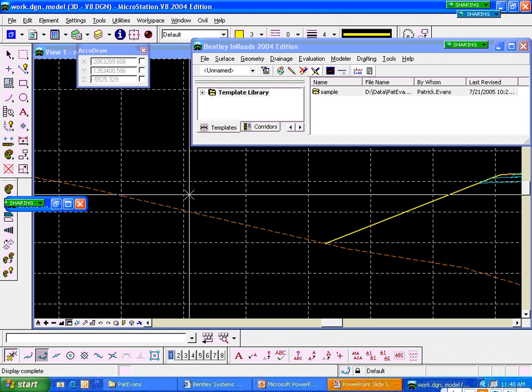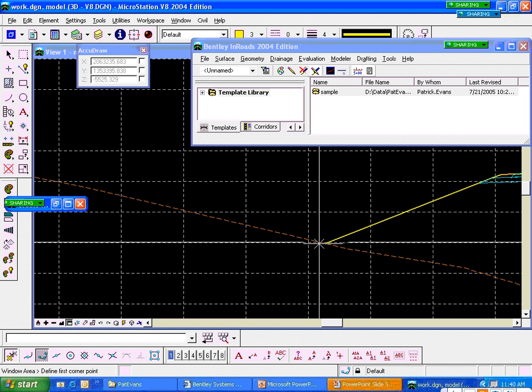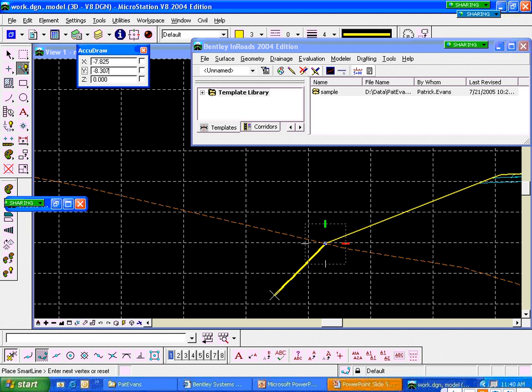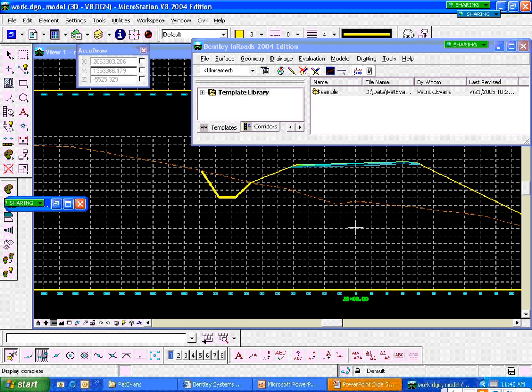And so really what I want to do is come over here. Let's window in a little bit. Since we are in a CAD package, let's go ahead and just draw what we want to happen here. I want to start at this point right here. I want to come in with a ditch like this, and then I want to tie back in up here, okay? And I want InRoads to do that for me. And that seems like a pretty logical thing to happen, because we're going to have to put a ditch in because we don't want the drainage to be right up against our embankment. So we can handle that pretty easily.